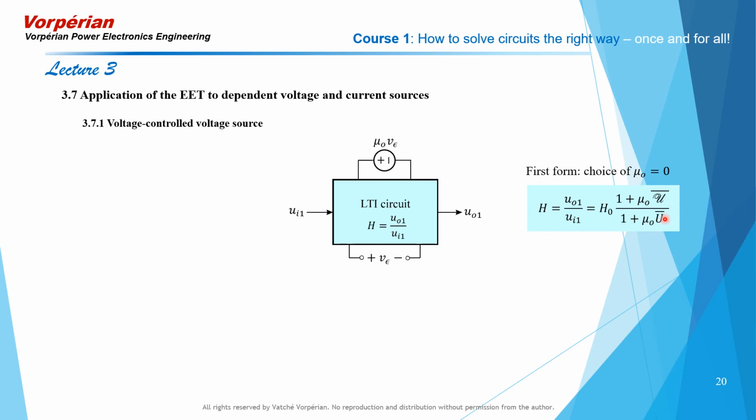These 2 computations are the same as the previous one, because they do not depend on how you choose to take the extra element out of the circuit, whether you take it out as 0 or as infinity. The only thing that changes is this factor that appears up front, and that's H0. And we show that in the following block diagram.